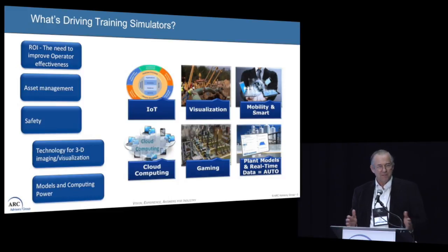You have to back off, and I would tend to advocate trying to keep the fidelity of the process part of the simulation down to a relatively low level. There's other aspects of training besides the training simulator itself that are needed. You will need to have operators that understand all of the health and safety issues, the environmental issues. You need to have them understand the chemistry in other ways that supplement the OTS. The OTS is not the only part of the operator training regime.